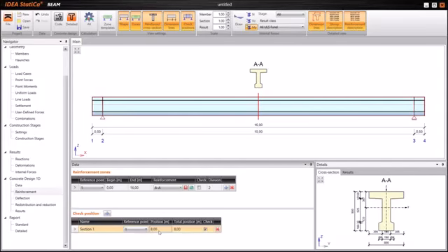As the program generates the sections according to both the geometry and the loads which are applied, I will use 7.99 just to avoid the case that in the middle the program generated a very small point load caused by the tendon due to some effects which we cannot explain here, and now I avoid generating two positions, one just before and one just after mid span.